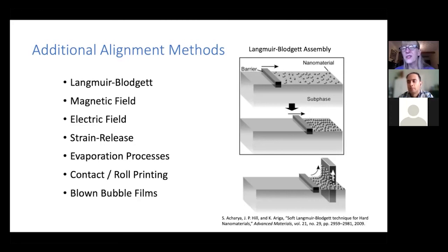Yeah, so you want to make sure, of course, that the fluid you choose for that interstitial gap meets a number of constraints. You've got to have good wetting. So in our case, it's an oil. We also wanted to make sure we could contrast the refractive index of the KLF microcrystals relative to the refractive index of the oil. We had to be sure we could actually see them when we put them under an optical microscope. So those are the sorts of compatibility questions you have to ask.